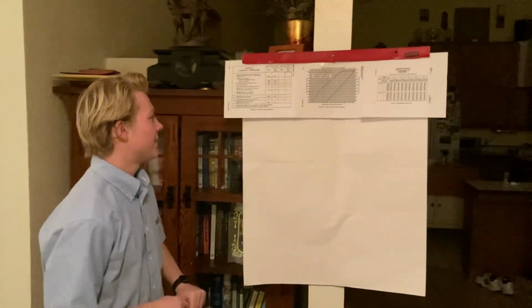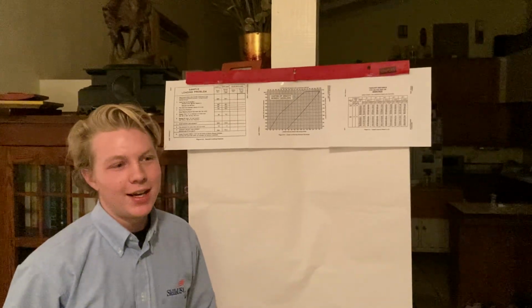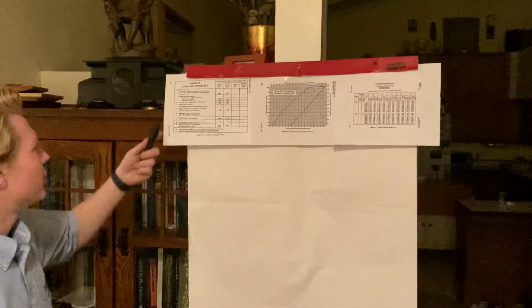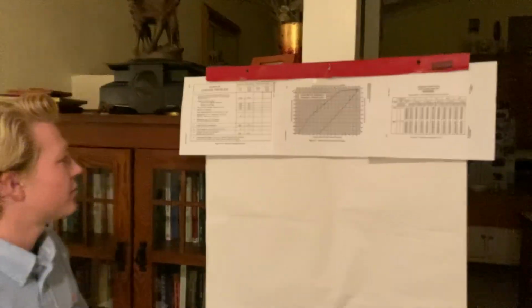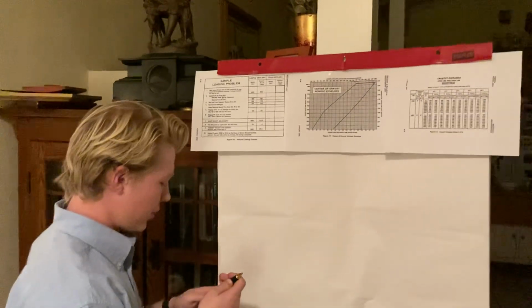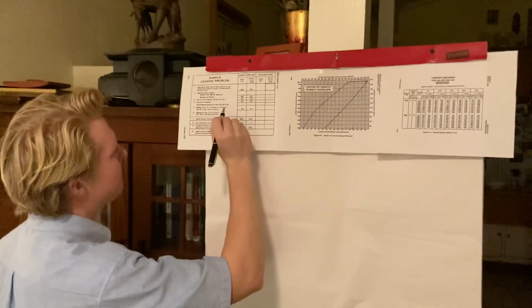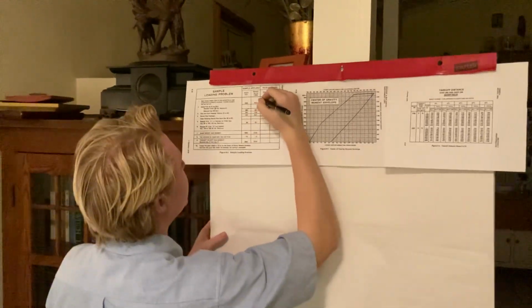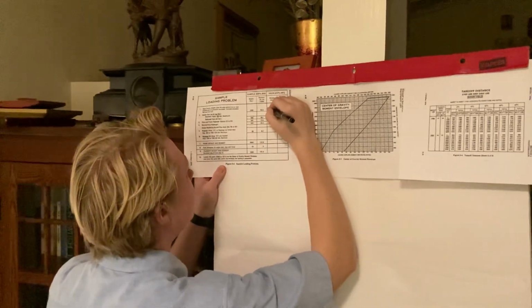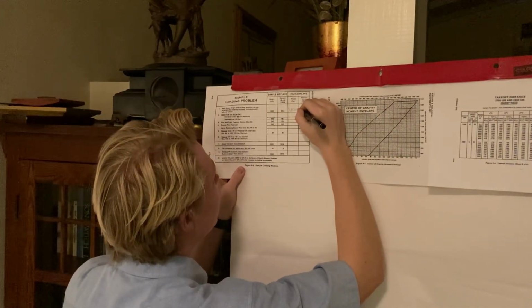So the airplane that we are using is a 1978 Cessna 182 Quebec. We have a sample loading problem of a weight and balance table from the pilot operating handbook. And so to complete that, it gives us our empty weight of 1,800 and our moment of 63.3.